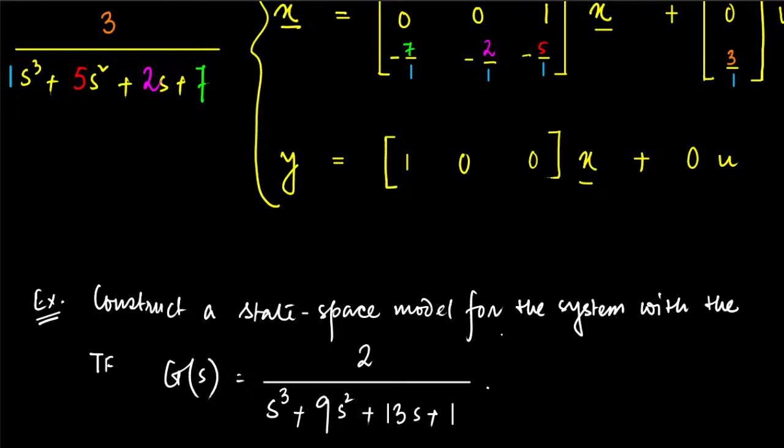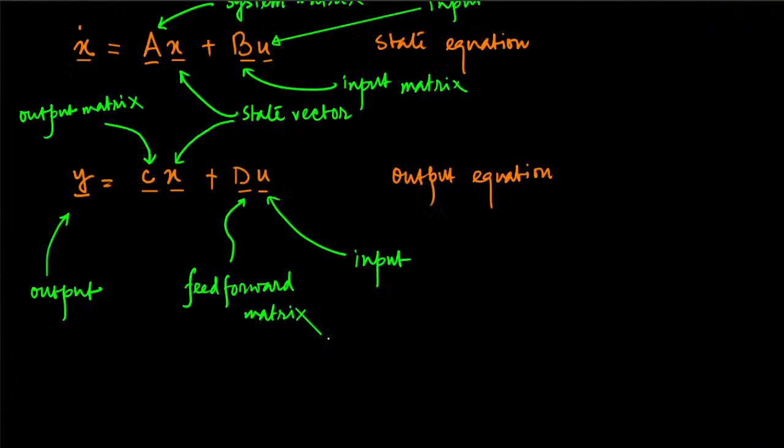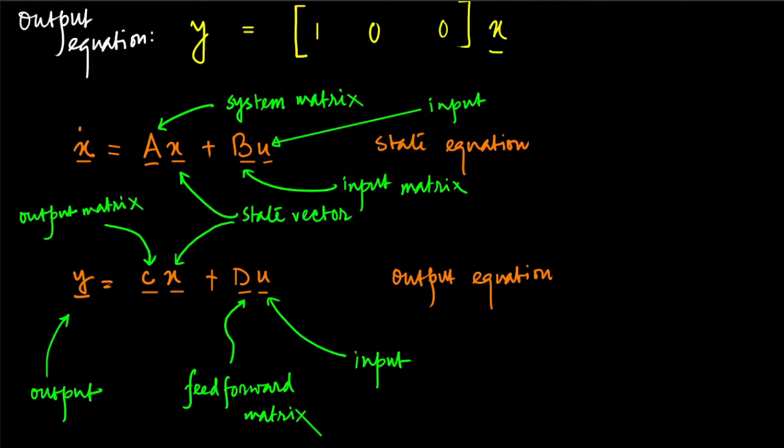And from there, we shall find out a standard way in which you can go back to the transfer function models as well. And then we're going to solve the state equation, because I said earlier that this set of equations, this very simple thing, x dot equal to ax plus bu and y equal to cx plus du, is so systematic that you can develop algorithms.